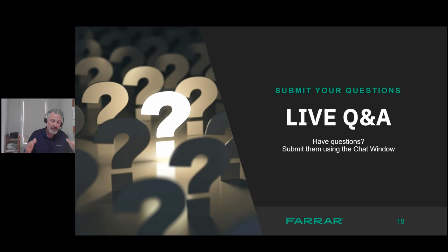So we're going to look at where the product's going to be stored, where your shelving racks are, obviously, things of this nature, and the proper placement for our sensors and where they're going to be. If you're non-redundant, typically we'll put it closest to the door because that's where you're going to see the first spike occur within a chamber, and your system needs to be responsible for that first spike that you're going to see. If it is a redundant system, it's going to generally go up closer to the ceiling,